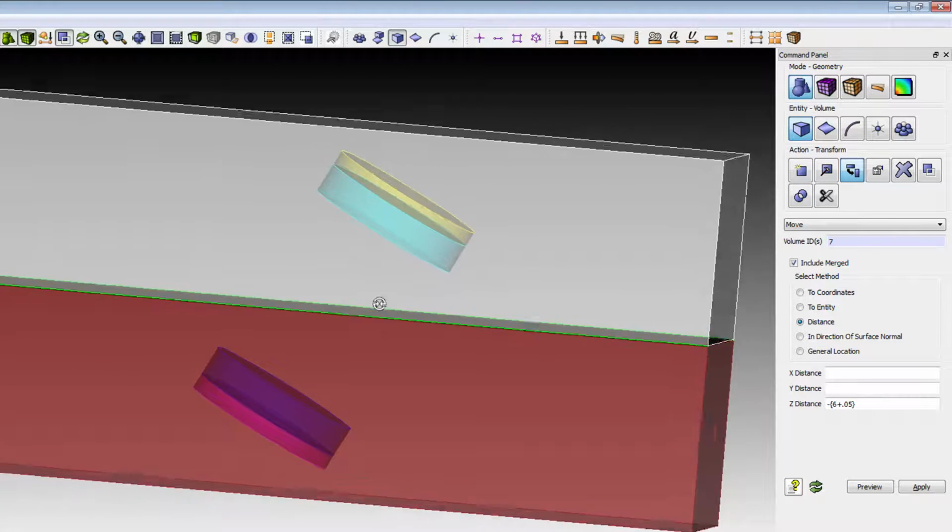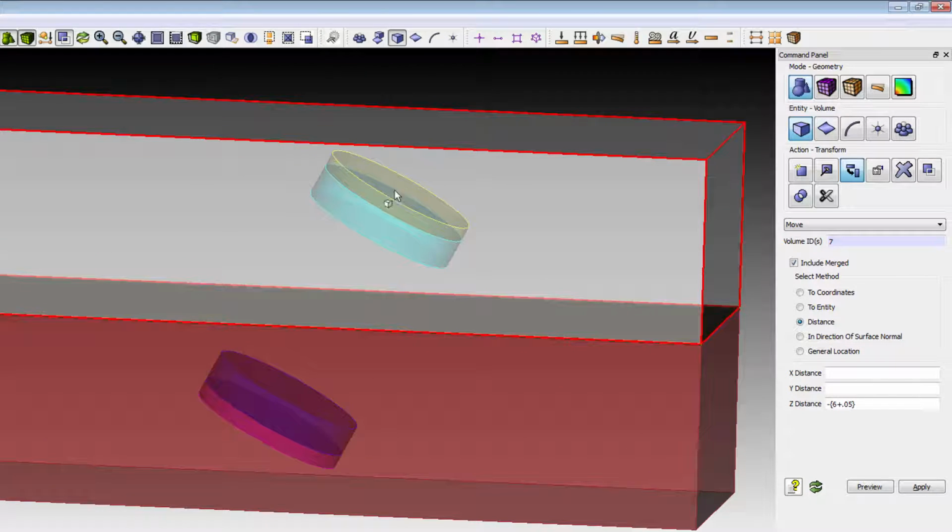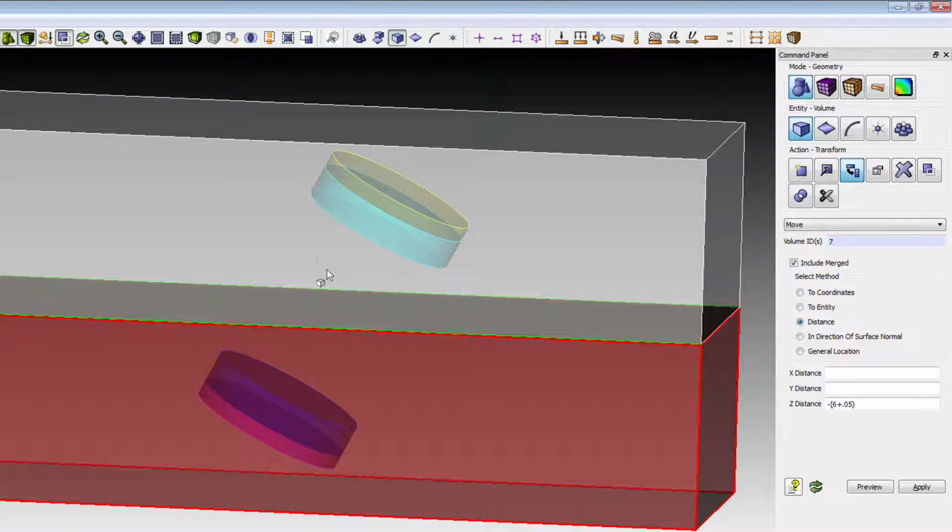Now there's still one thing missing, and this means here on the back side of the piezoelectric discs there should be no air, of course, because there's typically a housing or something like that. So we have to create some cylinders that will be placed here adjacent to the backside of the piezoelectric discs, and later on we will just subtract all of those cylindric volumes from the paper cubes.